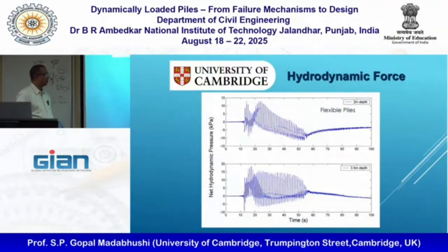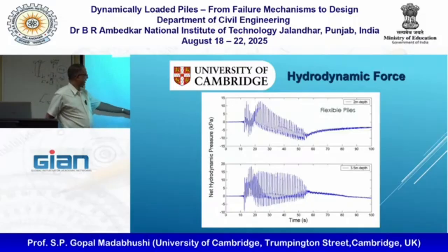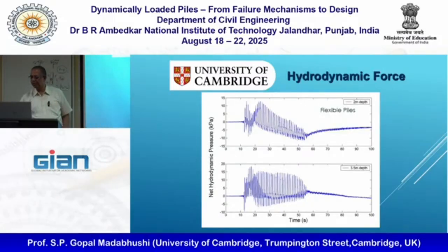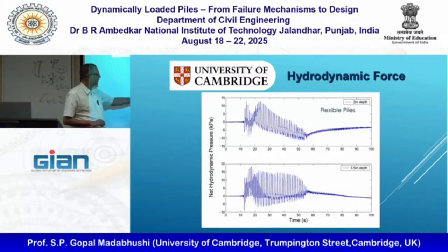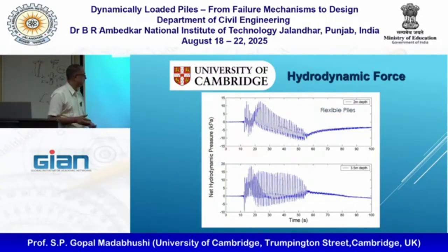Now, I can even work out how much hydrodynamic force I'm going to get, which will be the difference between the pore pressures at different elevations. And you can see how big these are. Again, these are calculations. Do you know why that is called that? Yeah, okay. So flexible pile and different depths. These are basically plotted as the difference between the two pore pressures on either side. This is the direct force the pile will feel.